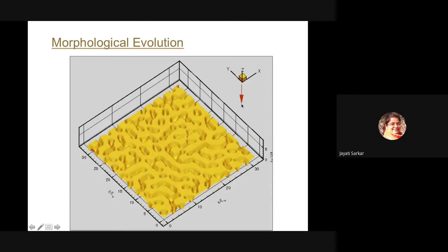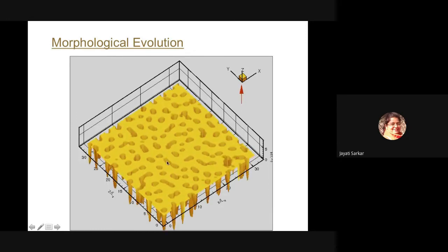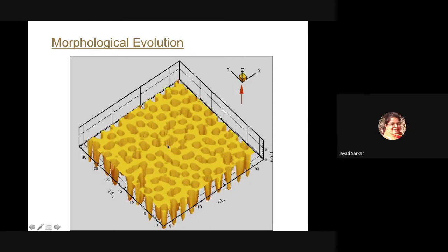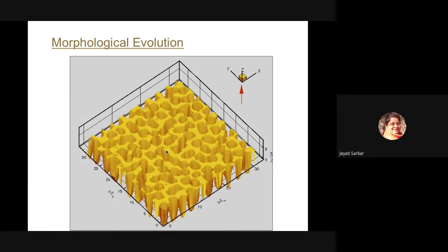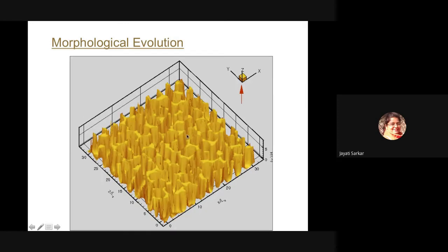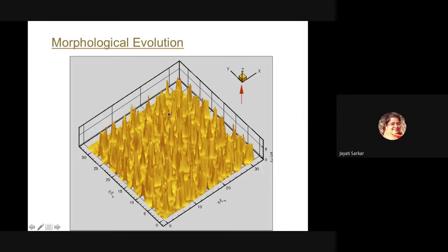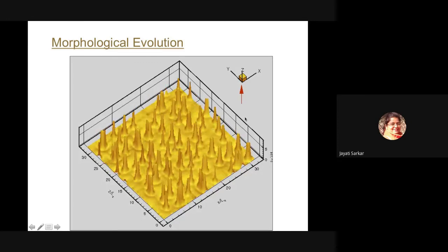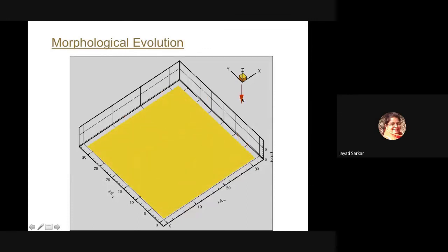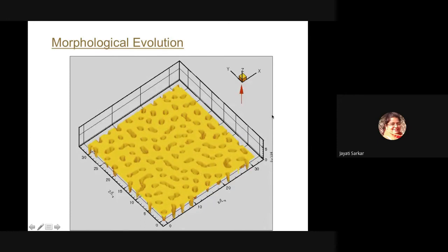So if this was the critical distance where the instabilities had started, you can see that these cavities are joining, right? So there is a total landscape change of these patterns that are forming. And then you can bring it and you can actually freeze these patterns at any stage. Then you can see the total range of patterns that you can create out of these elastic films if you can freeze these patterns. And of course the snap-off distance is much higher than the critical distance at which it initiates.